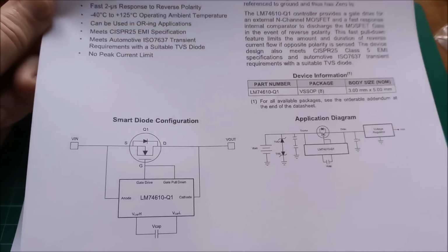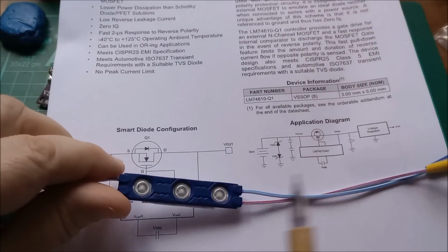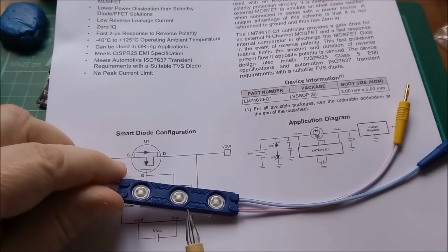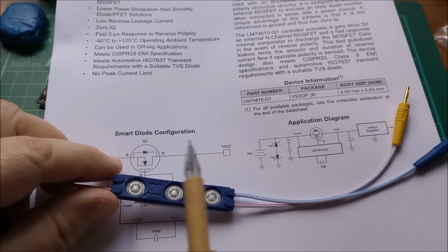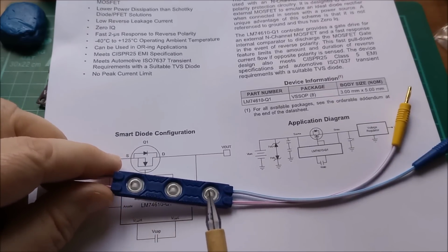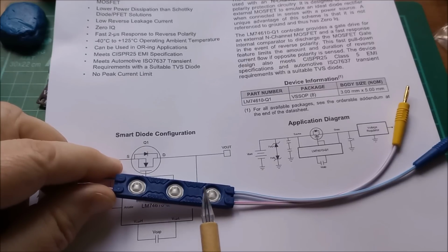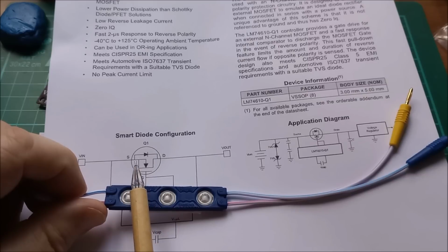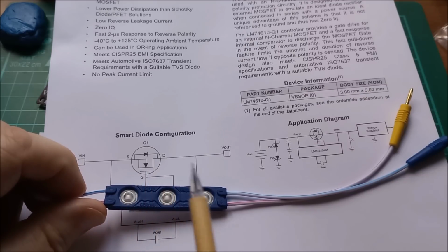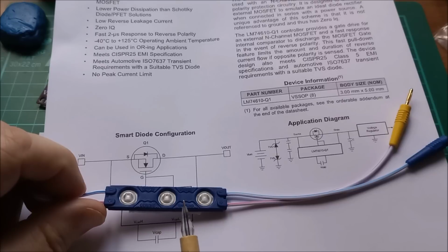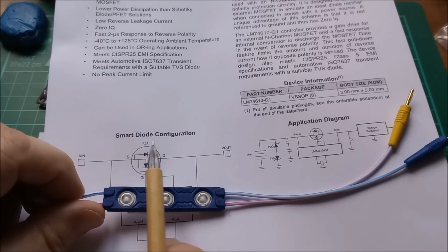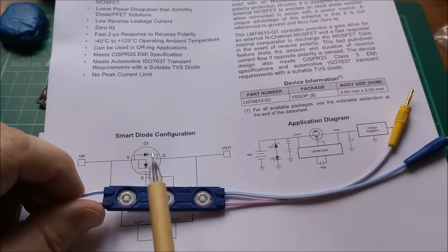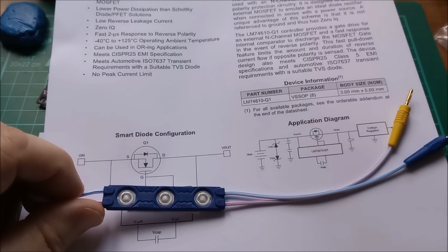And so that's why in the beginning of this video you saw this LED pulsing. Now the pulsing was exaggerated, but I'll put that system back on after I finish this video, and we'll see that actually the off or the body diode conduction time is very short, and the MOSFET conduction channel on time is much longer. In fact, it's 98% of the duty cycle. So it only is passing current through the body diode for a very short period of time. It's not long enough for it to warm up significantly.